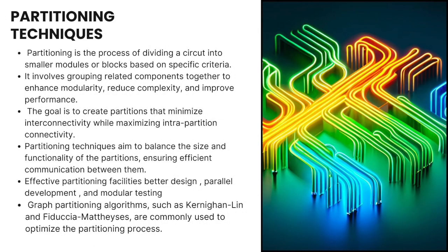And now let us learn partitioning. Partitioning is the first step for VLSI physical design. Partitioning is the process of dividing a circuit into smaller modules or sub-circuits based on some criteria. Partitioning is nothing but grouping related components to improve performance and reduce complexity.